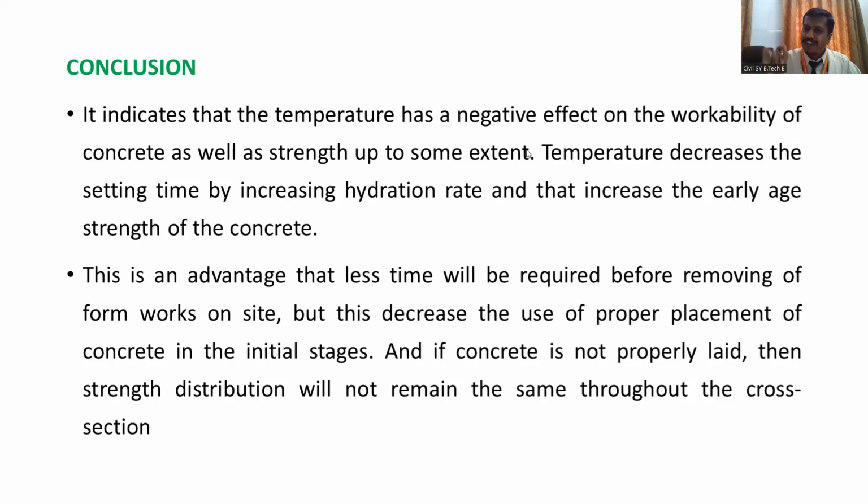The concrete will remain in the fresh stage for a long time. And you can connect the two different layers of the concrete with each other in such condition. That is why we are preferring concreting at night as far as roads and rigid pavements are considered. That concrete will remain in its workable, plastic condition for a long time. A long time means not that much so long. Okay, but you can connect the two different slab sections together. There will be good bonding as both concrete are in fresh condition.